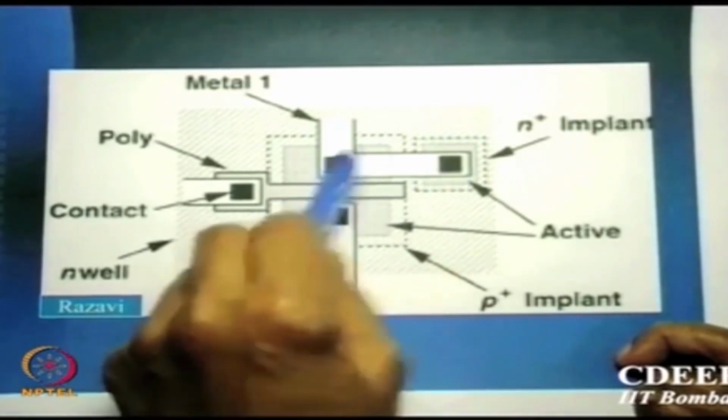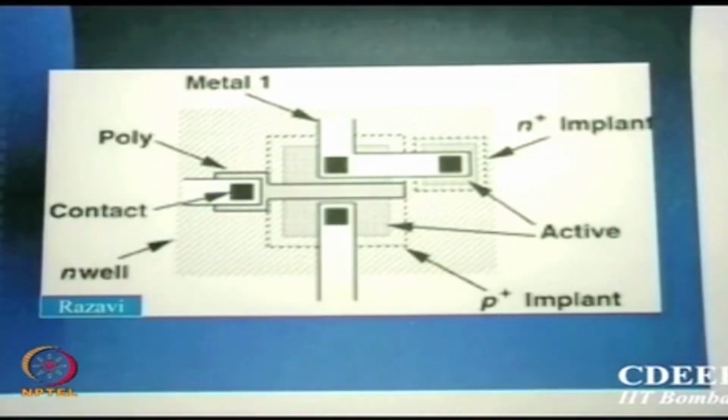The method is that any metal 1 normally runs vertical, any metal 2 runs horizontal. Normally they are not running in the same direction, and no angles. A layout should never be at 45 degrees or 30 degrees. The normal XY system of parallel coordinates is always used. These lines are called Manhattan lines.